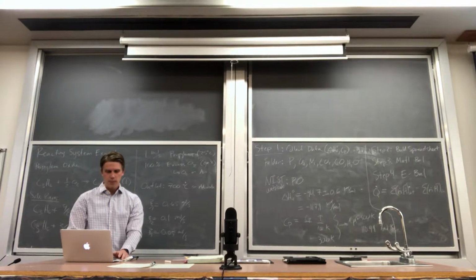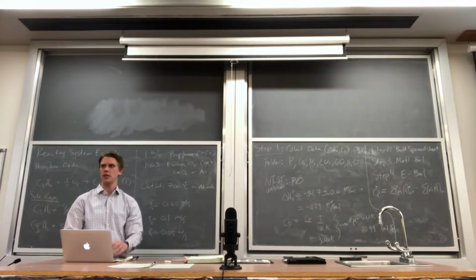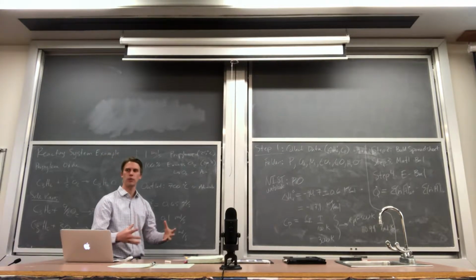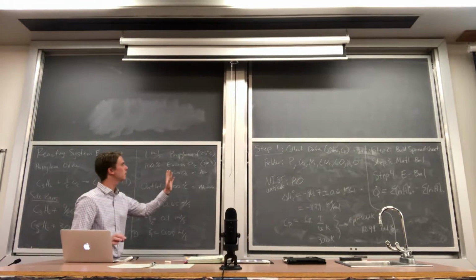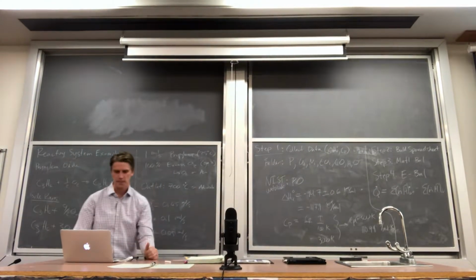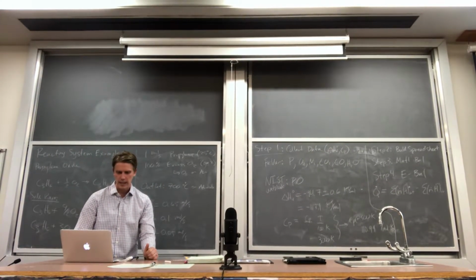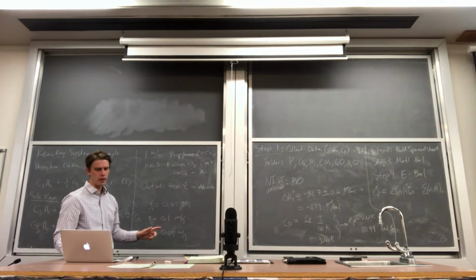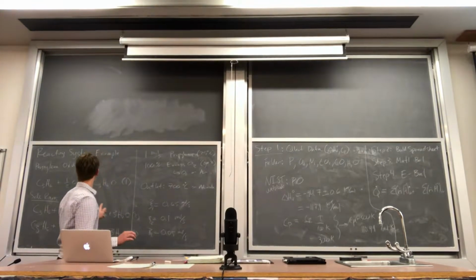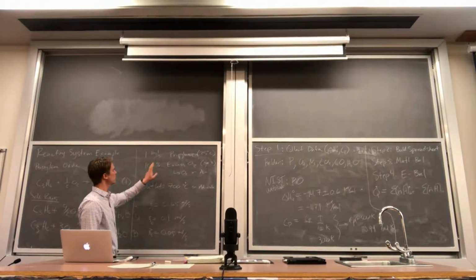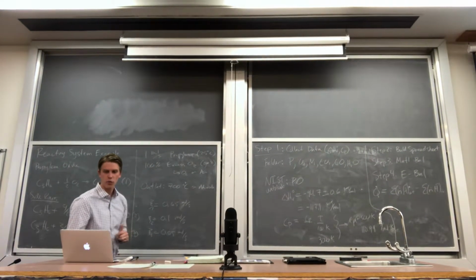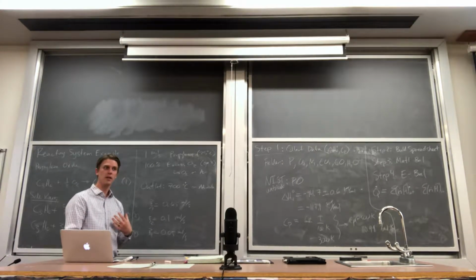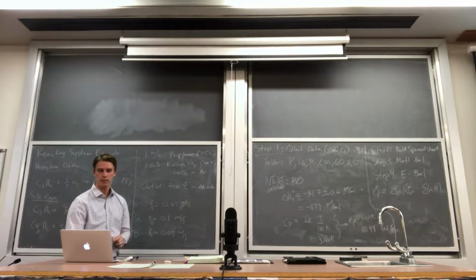So how I build my spreadsheet is just really algorithmic, and I basically march through the process as if we're going from start to finish. So I enter in my flow rates. Propylene, I have 1, right? That's our basis. We have 100% excess oxygen. So if I go to this gray colored cell, that's telling me that this is a formula that I entered in that accounts for the reaction.